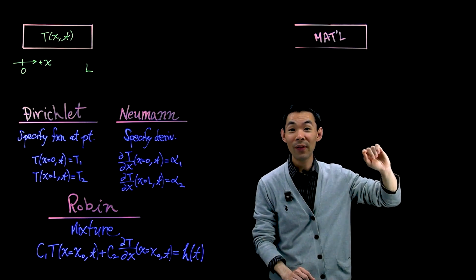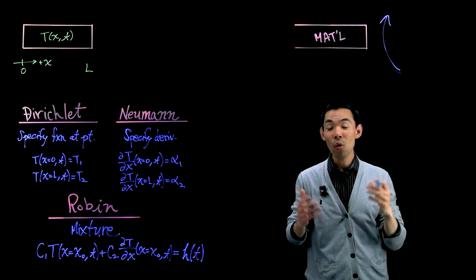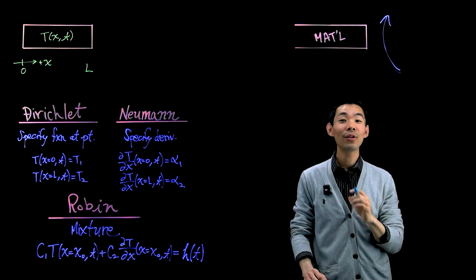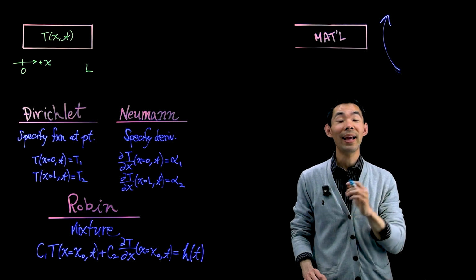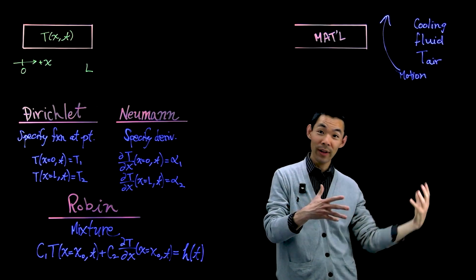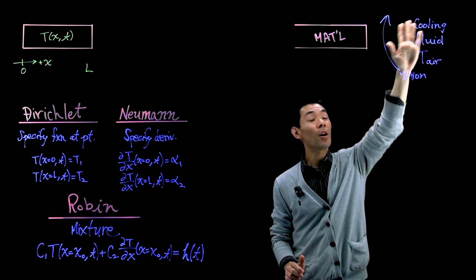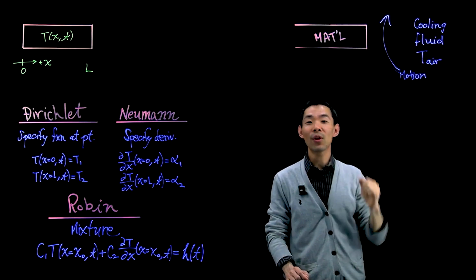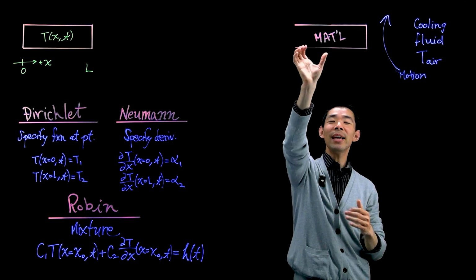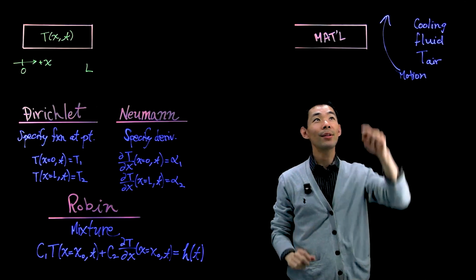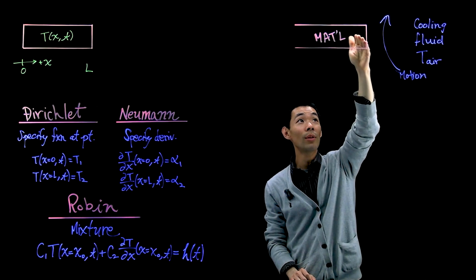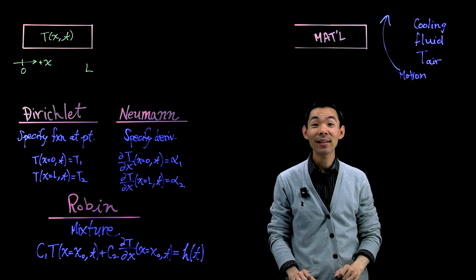So there's going to be some convective cooling of air or some kind of fluid at the end or across the surface of your material to prevent the temperature from getting too high. So let's suppose it's air. There's some fan that's blowing on your laptop or inside of your computer that's blowing a colder air across your surface that's overheating. Now, when you want to solve for the temperature profile inside your material, there's going to be a Fourier's constitutive relation, Fourier's law of conduction, that you would need to apply right at the boundary at x equal to L.